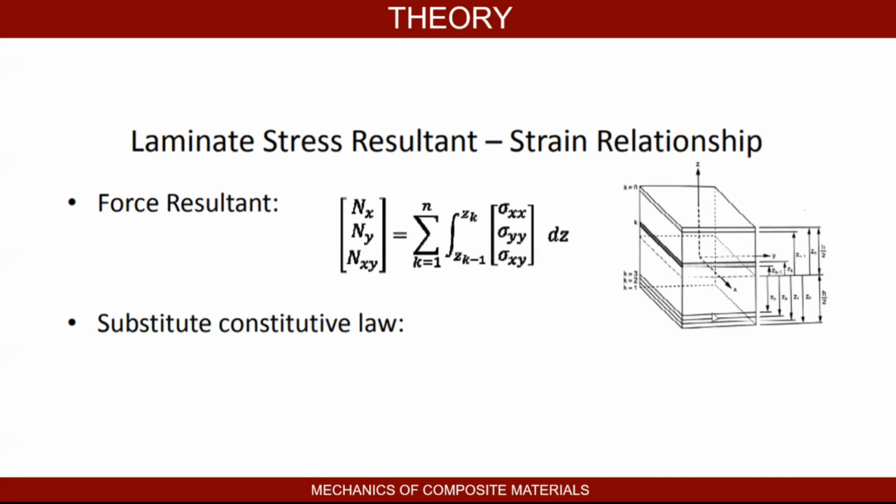If you have a very thick lamina, it can lie somewhere in the middle of your lamina. But starting at the midplane, you effectively want to develop boundaries for each lamina or each layer. So here you have Z K minus 1 is the top of this layer, and then Z naught is the bottom. And then working up to the next one, you have ZK is the top of this layer, and ZK minus 1 is the bottom. So that might come into play once I pull up my Excel sheet,